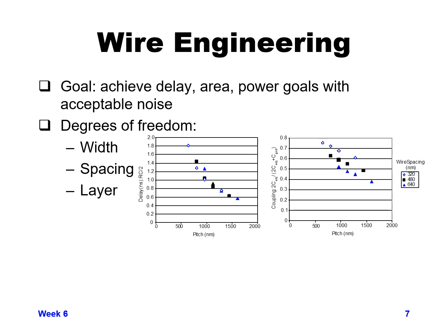Then of course the metal layer that you're using, higher metal layers tend to have lower resistance and the capacitance might be approximately the same, but because the higher layers have taller wires, it's not always the case that a higher metal layer has less capacitance. It all depends on exactly how much the spacing between your wires is, because the thickness is definitely higher. So overall you could have a higher capacitance if the spacing is equal to a lower metal layer.